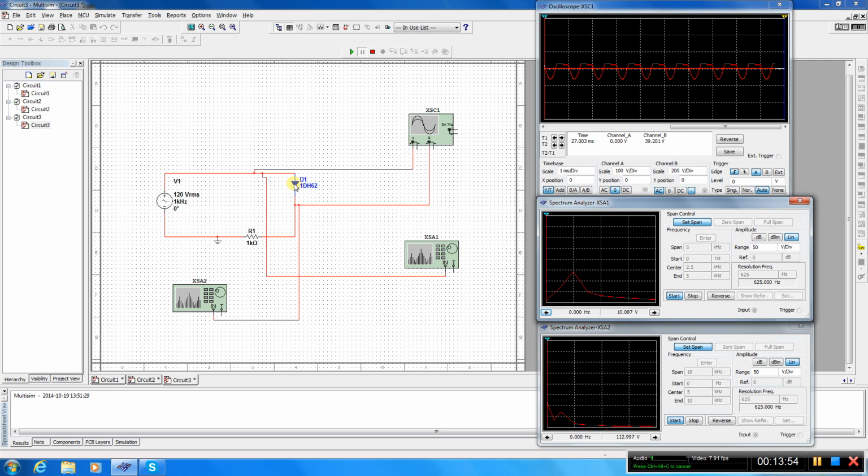One diode probably will be enough, and also a filter which consists of capacitors and an inductor. So you should somehow design this circuit to get a sine wave as an output, but the frequency of it should be 2 times greater than we have now. So not 1 kilohertz but 2 kilohertz.